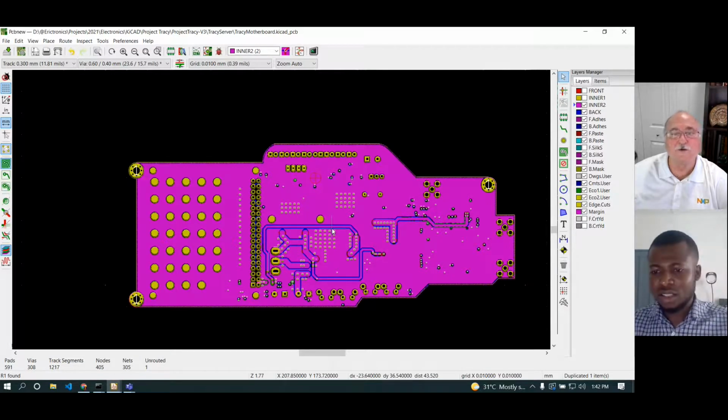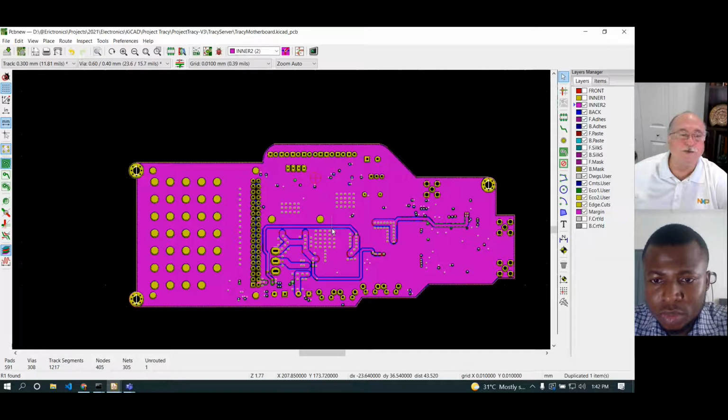That's excellent. So what I want to highlight here is that this leaves most of this layer behaving as if it was a ground plane. And the power supplies that are routed on this are adjacent to the ground copper on layer 2, so they're all well behaved. They're also a copy of the copper that's on layer 1, so that's where he's provided 2 paths for the energy, which reduces the impedance by 50% and increases the energy per wave cycle to 200% of what you would get from a single one.